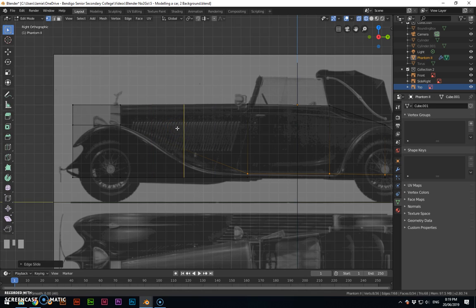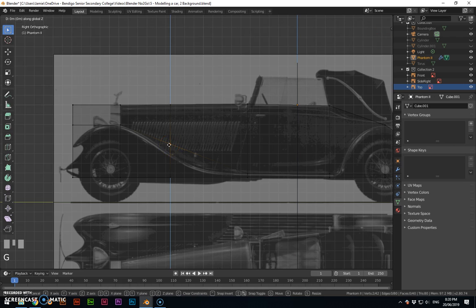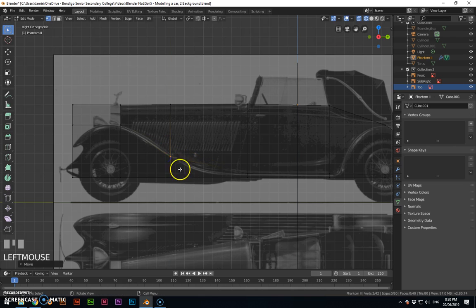and extra detail to basically say, well, where do I want that to hit? Probably the point where it changes from one style of curve into another. So through here it's curving in that way, but in here it's curving down, and there's a point halfway where it flows from one curve into the other. So picking that midpoint is actually of benefit, and then grab in the Z direction and pull that down to match. And as I do, I can get this topology closer and closer to the shape of the car. And this is really what happens when you're modelling, is you start with an idea and you then get closer and closer to what you're working on.